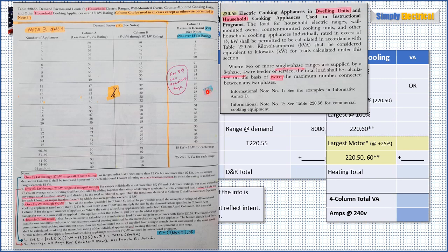That's a kilowatt value. That makes a big difference because say you're doing multifamily and you're looking at 20 units, and you come over here to column B and say, oh yeah, 28 kilowatts. Well, no, it wasn't 28 kilowatts, it's 28%. That's a big difference, or it could be. Or you could go over here and say, oh yeah, 35%. Well, it's not 35%, it's 35 kilowatts. So again, that could make a big difference in your calculation. So you've got to be cognizant that we're talking about different values in these columns here.